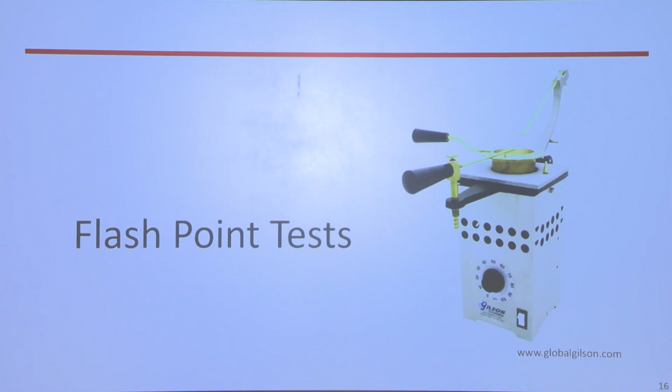We use thermocouples to measure the temperature inside the liquid because it's so much easier, but the standard test actually has a long mercury thermometer that hangs down into the pool, but you want to make sure that you know your pool temperature. And then on the front here, with this black handle with the brass tube, is a flame that you pass over the cup. You can see feeding into the bottom of that handle, there's a barb fitting. You can slide a flex hose over it and provide methane or propane as your flame.